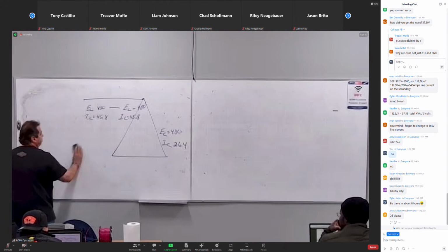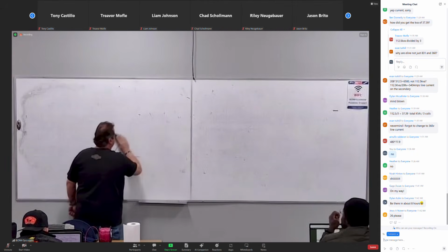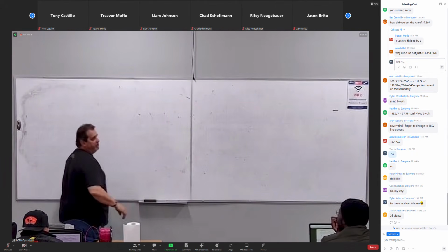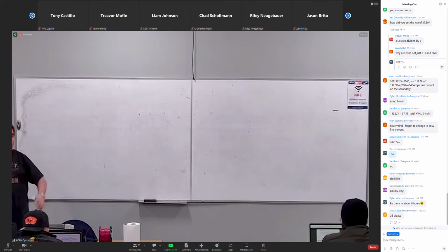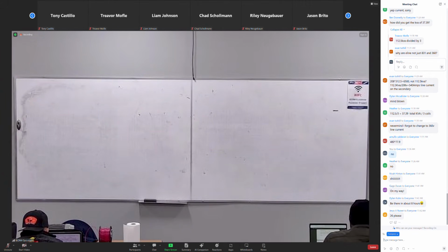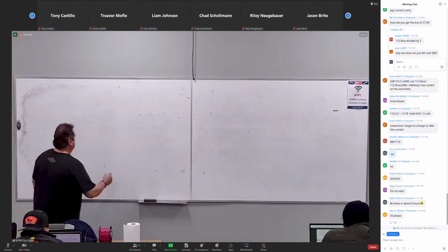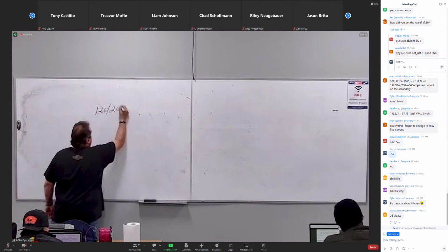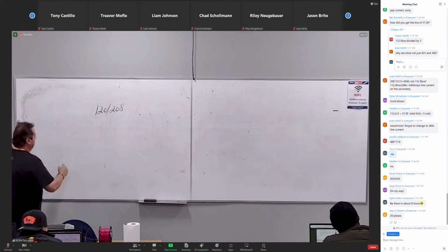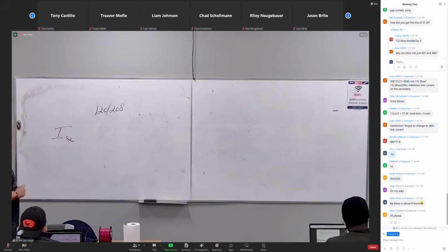That question is the short circuit fault current question. They sound really complicated because look at all the information. We had a 480 volt transformer, and so on. The secondary is what voltage? 120/208. So basically they're saying, look, I have a 120/208 volt system. I have a fault current. I want to know I. Now the I is going to be short circuit.